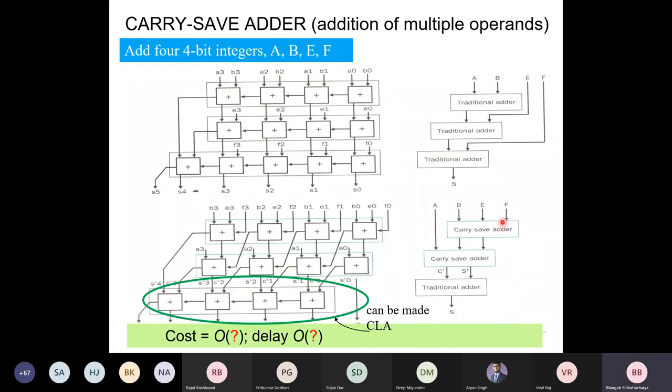How does it look like? Isn't it a serial chain? This is a block and then a new input appears, and then another new input appears here. So it's like a chain, right? Whenever you have a chain of signal flow, can you do it better to process the newer inputs? The carry look ahead is to expedite the last stage. But can I change this? This is a linear chain, right? Because at each level you are processing a newer input.